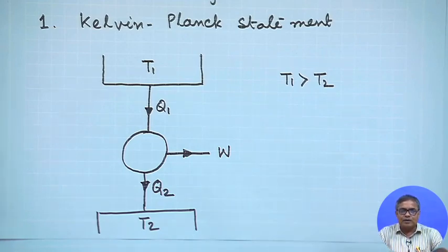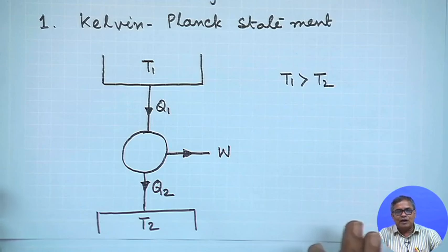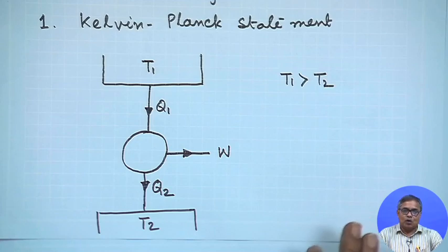So, coal is burnt, thermal energy is produced. So, we can idealize it as if it is a reservoir with a constant temperature. So, then with the help of that heat or at that high temperature, water will be converted into steam. The steam will be made to pass through a turbine, the turbine will rotate and produce mechanical energy. Then the steam which is at low pressure and low temperature will come out of the turbine and we will condense it. When we are condensing it, what we are doing? We are rejecting heat to the atmosphere.